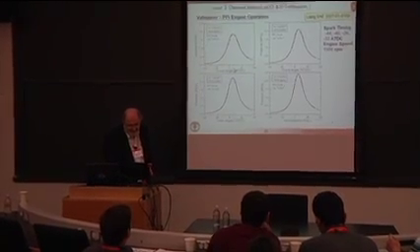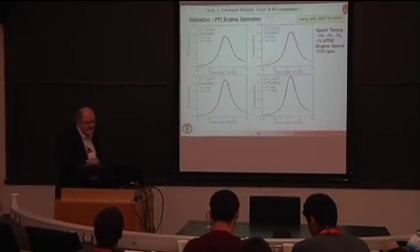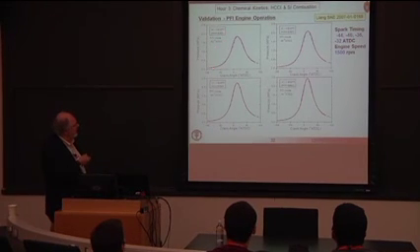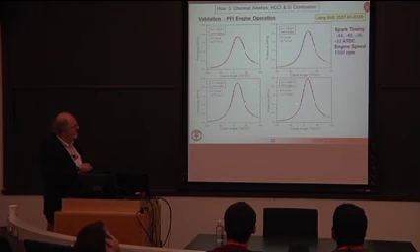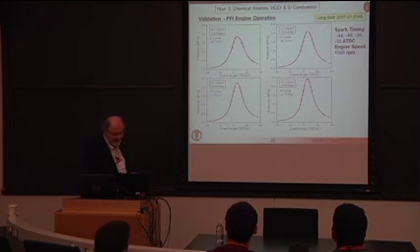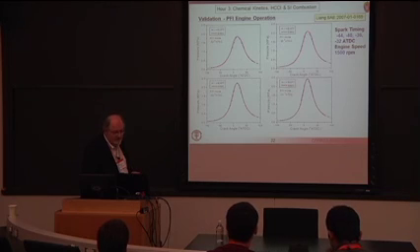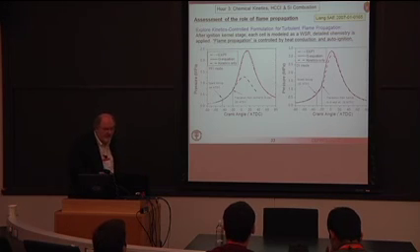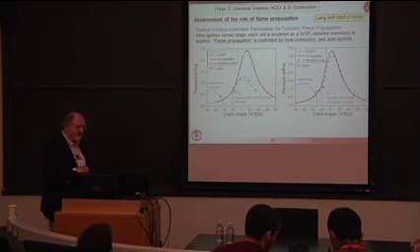And then finally, here are some validation results from engine experiments described in this paper. Cylinder pressure versus crank angle for the different spark timings. You see very nice agreement over a wide range of operating conditions. These models are now used widely, and this work was funded by Ford, so they use this a lot for their engine design.